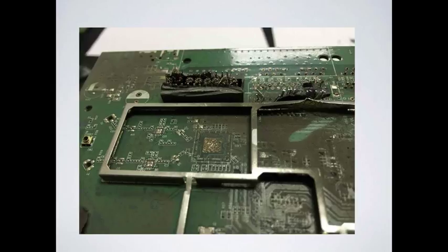Once you get the cap off, you can pull those black things up, and then once you get that out, you can flip the board over and heat it with a heat gun on the other side and just pull the wires out. That was the easiest way to get it off. And then just use the heat gun to remove all the little capacitors. That's what I used the tweezers for, and the magnifying glass. Heat it up and then just start rubbing away at it, and they all come off.